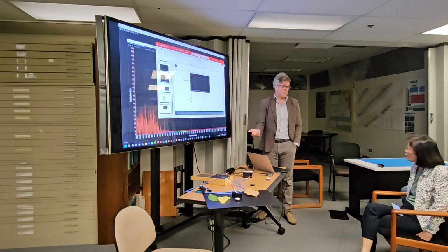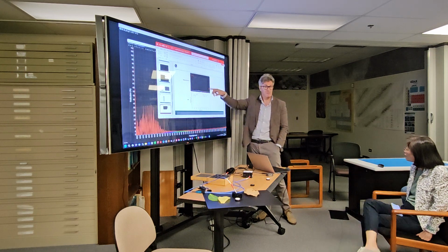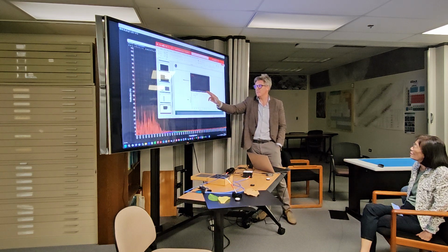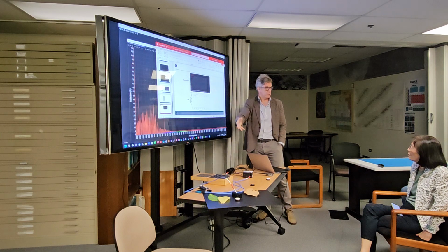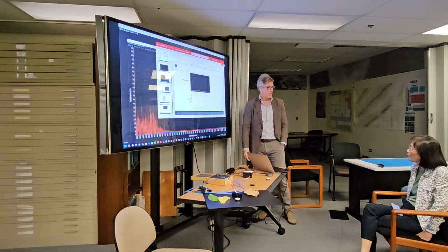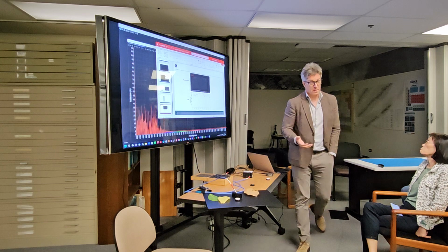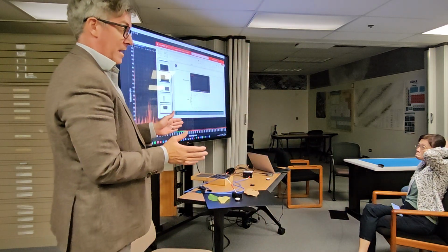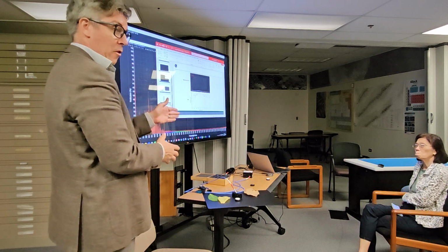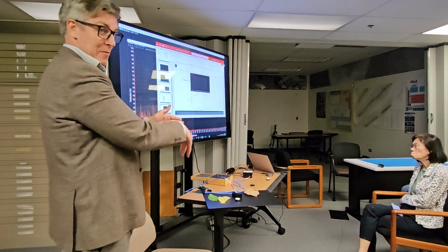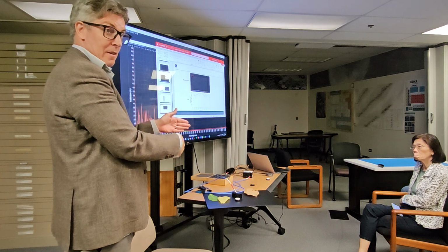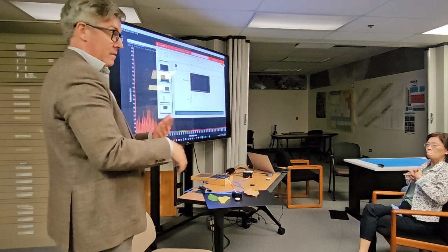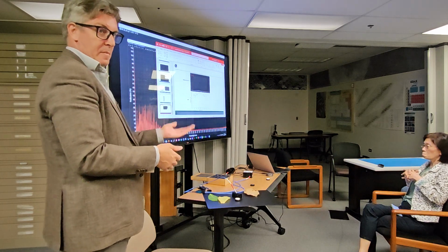And in 200 days, I should be able to replicate this measurement, right? And if it's got more noisy, or if the spectral location of these peaks has moved, then I know there's a problem with my spectrometer, right? So this is a reason when you launch instruments into space, you tend to have onboard calibration, right? You tend to have a target on the spacecraft that the camera can look at and say, I know what I should be measuring from you. Am I still measuring that signal, right? And if you are, then great. If not, then the people on the ground have to work out a fix to recalibrate the data.